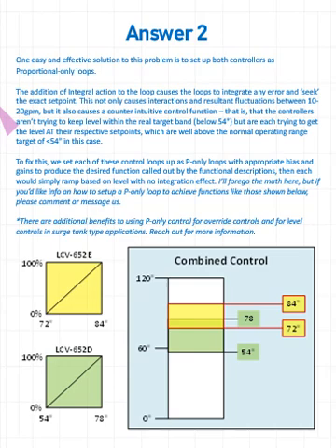So in this case, the big valve starts opening at 72 inches and it's full open at 84. So there's a little bit of overlap there. There could be more, there could be less. But basically, because you remove the integral function on a proportional only controller, it's not trying to seek the center point. It's going to allow it to just rise up.